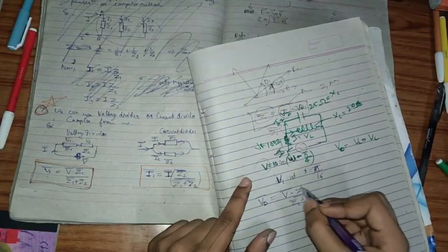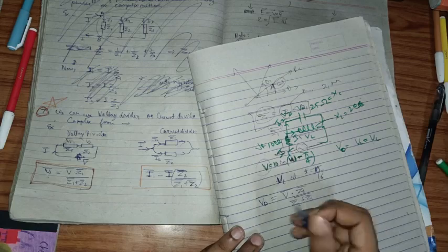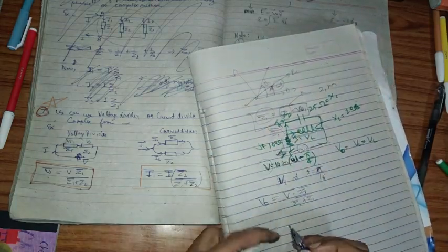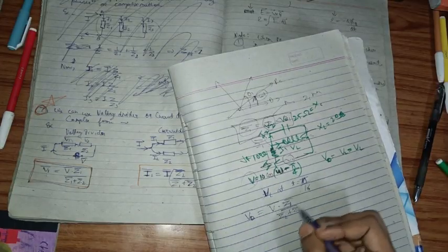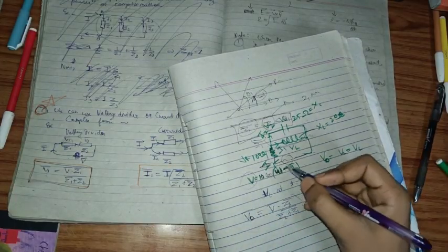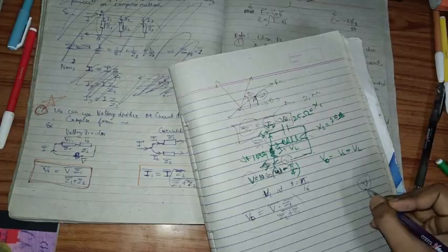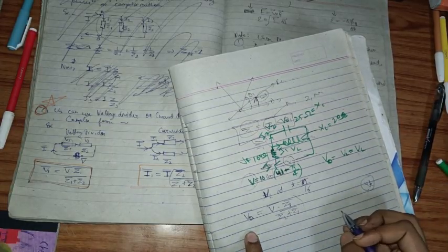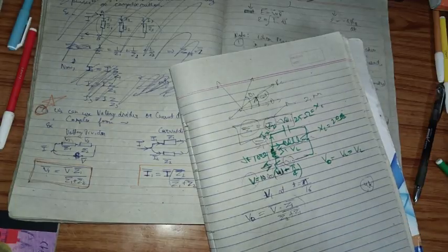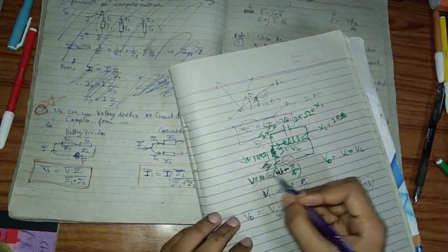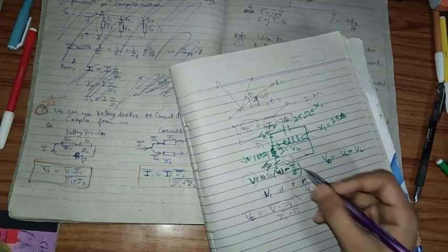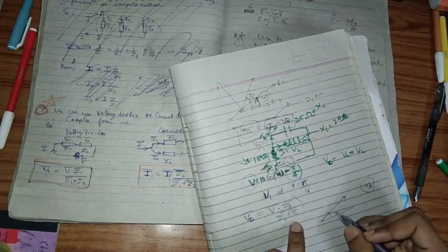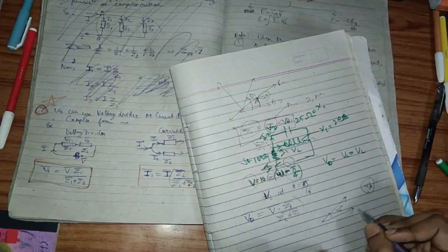the voltage becomes, with this cos function, a phase of minus π/4. With this reference frame, the voltage is actually π/4, or 45 degrees, behind. This is the voltage of the source, and this is Z1, which is made from 25 and 20. These two are parallel, so 1 upon Z1 will be calculated as 1 upon XC plus 1 upon XL.